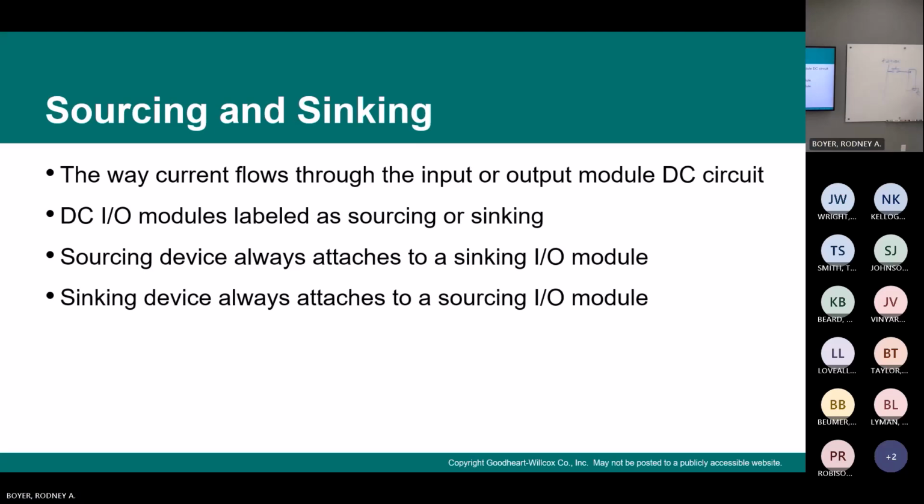The current is going to go from the plus 24 volts through the switch to ground, so it is sinking.